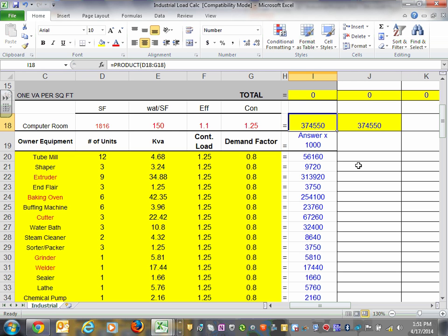If you don't have this in your building, what do you do? Zero it, right? You don't have to have this. If you're using the racks, like we're using next year, you put how many racks you have here, say 24 racks, and multiply them by the volt-amps per rack, and increase them 10% for the most part. And you can argue with the 10%. You can get this from the manufacturer. But that's kind of a cover-your-butt type of design. You know, you don't know a whole lot about the system.